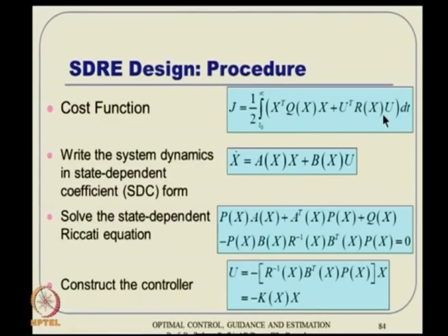So, the idea here is, we can treat for a moment that at any particular grid point it is actually a quadratic regulator problem, and hence we go back to the LQR theory and solve the required Riccati equation at every grid point online. Then whatever positive definite P matrix comes out of that, I can use it in this formulation and compute a gain K. But remember, K is now a function of x, because at every grid point it has to take a different value. So, we essentially come up with a nonlinear controller, but with a linear looking structure.